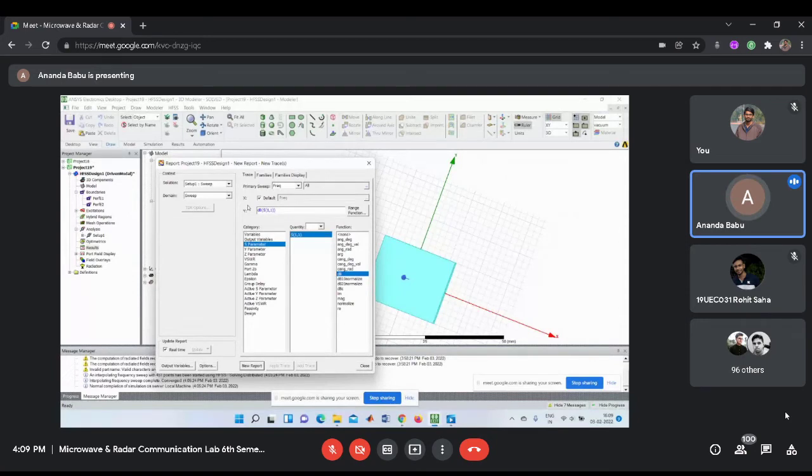You are giving the input source, and based on it, how much is reflected back. Suppose you design an antenna and give the excitation, the RF input signal, that means radio frequency input signal to the antenna. How much is radiated, we cannot find out directly. So whatever input we give, already we are giving 50 ohms impedance, as previously shown in the excitation.